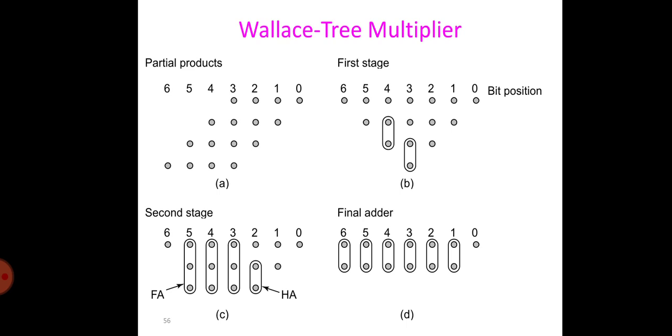A number of compression circuits have been proposed, and they are all based on the concept that when full adders are used as 3:2 compressors, the number of partial products is reduced by 2/3 at each multiplier stage. And one can even go a step further and devise a 4:2 compressor, such as the Santoro compressor. In fact, many of today's high performance multipliers do just that.